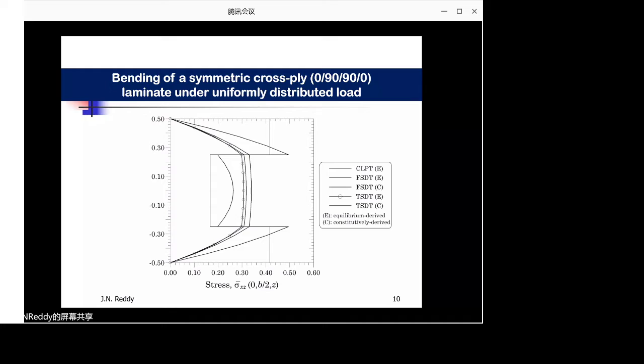Three stresses on that plane. So if the sigma xz exceeds the allowable for the material glue that is connecting two layers, then it will delaminate. And whereas if it exceeds sigma xz or yz allowable, then it will also delaminate by shear.